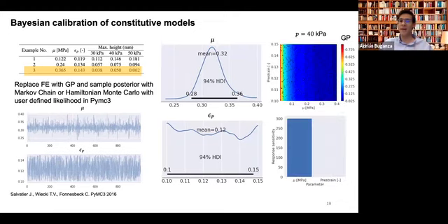Because if you look at the contour of the measurement as a function of the pre-strain and the shear modulus, and if you do a sensitivity analysis, you will see that the shear modulus is way more important. And actually, in the small shear modulus region is where you have the greatest variation. As you increase the shear modulus, you have less and less variation. So yes, it's right. If I get a posterior distribution of the pre-strain, it should be very flat because I really cannot tell what the difference is between one pre-strain or another, whereas I can tell a little bit more about the shear modulus.